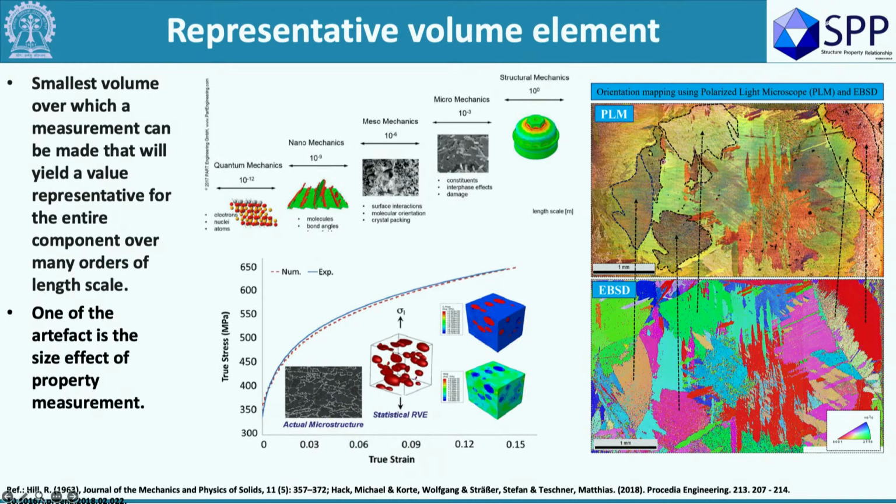A standard sample, you determine out of 3 maybe, for better statistics, and that value is going into making that bridge. So you have to make sure that this testing you are doing with a simple specimen in your lab carries the same kind of information, valid for that larger structure. That's the representative volume element problem.